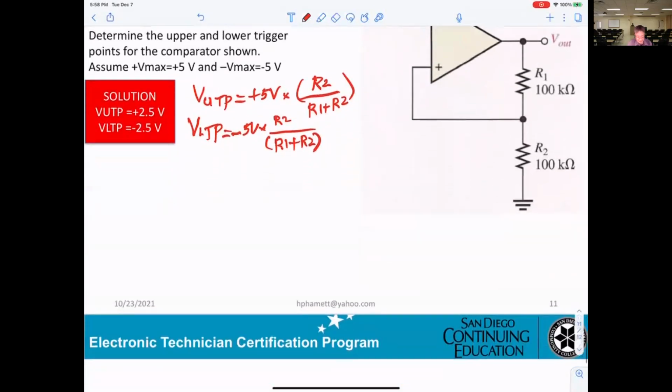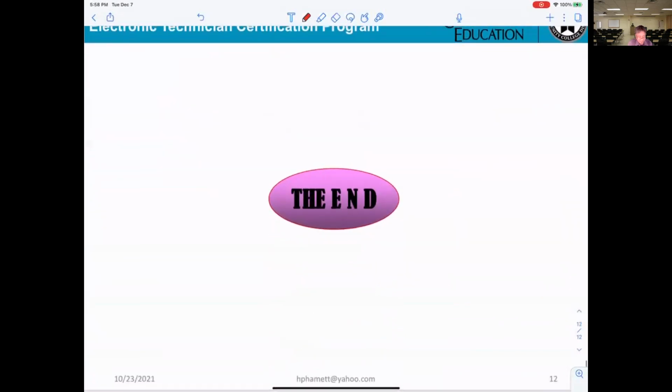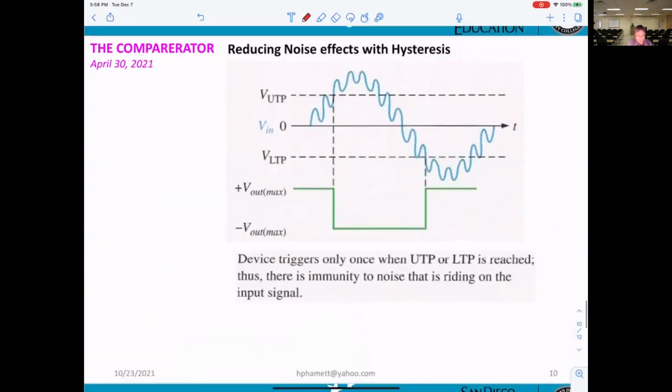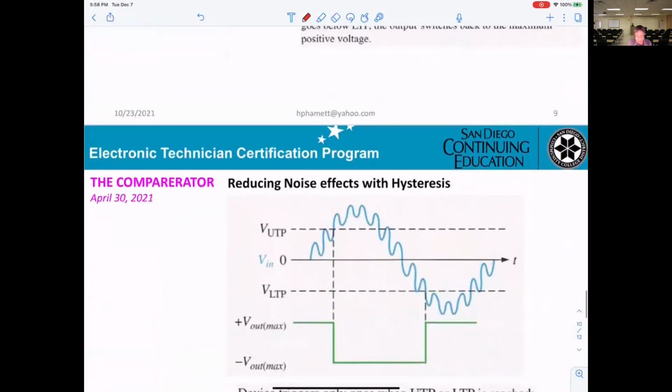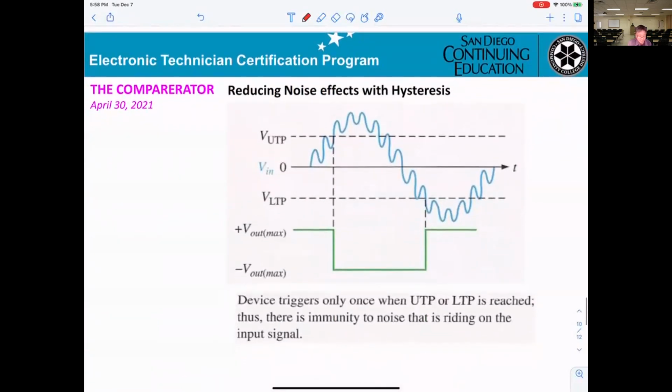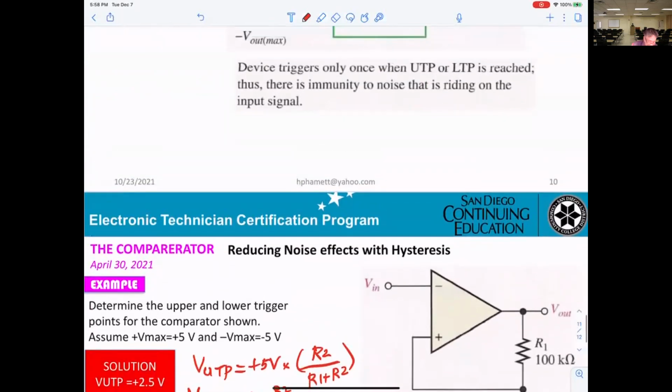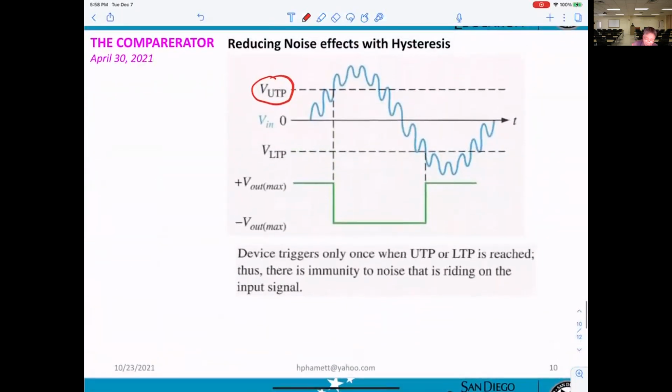Okay, let's see what's going on here. Depending on the signal they give you, you're able to get the output. How do we get it? First thing, you need to draw the upper trigger. Like if you calculate here, it is 2.5, so you get 2.5 volt here.